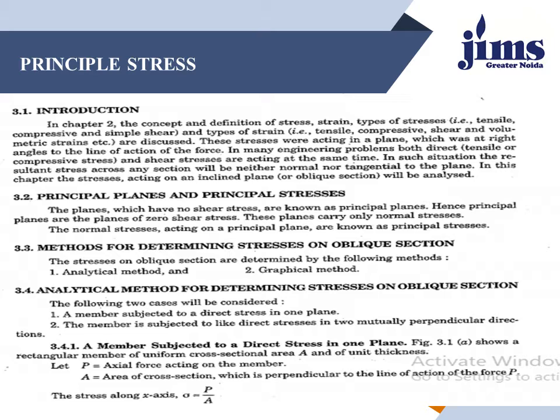These stresses were acting in a plane which was at a right angle to the line of action of the force. In many engineering problems, both direct stress, that is tensile or compressive stress, and shear stress are acting at the same time. In such a situation, the resultant stress across any section will be neither normal nor tangential to the plane. In this lecture, the stresses acting on an inclined plane will be discussed.